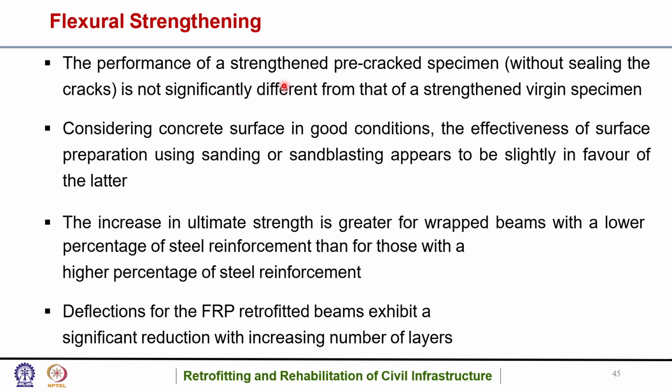The performance of a strengthened pre-crack specimen without sealing the cracks is not significantly different from that of a strengthened virgin or sound specimen, unstressed. And considering concrete surface in good conditions, the effectiveness of surface preparation using sanding or sandblasting appears to be slightly in favor of the latter.